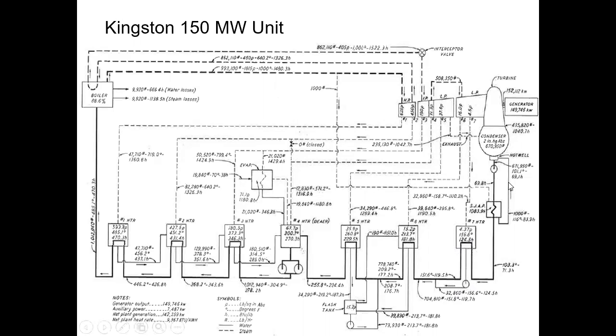Looks like 671,950 out of here. So anyway, that's how it is possible. I could put in a pump and pump this condensate back into the line like I'm doing down here. But on these higher pressure heaters, they just let it flow naturally back to the open heater, and then it joins the feed water there.